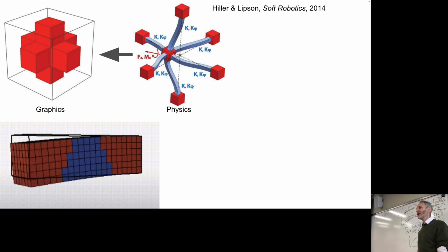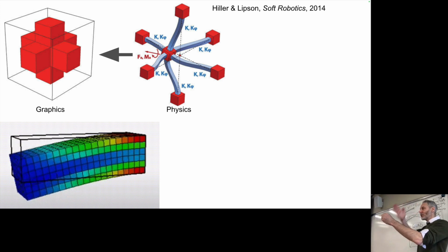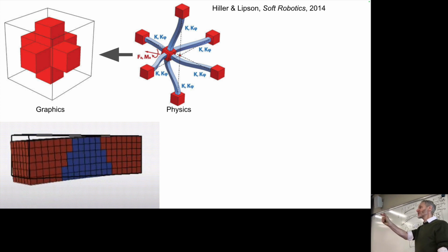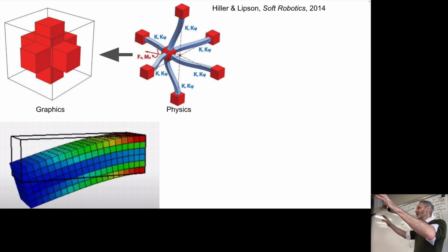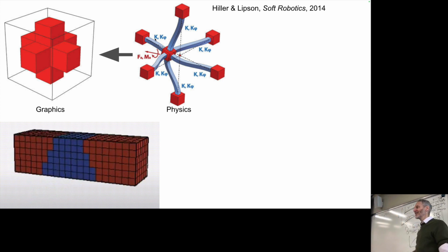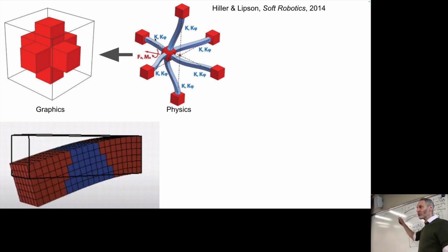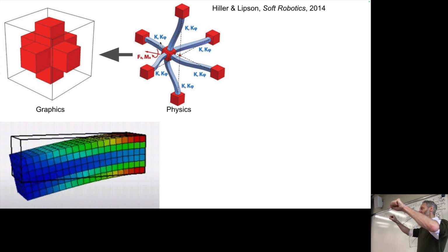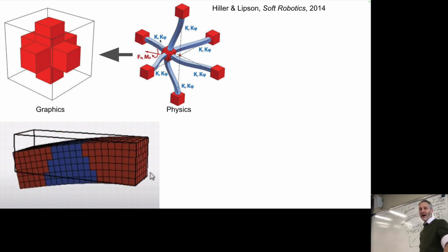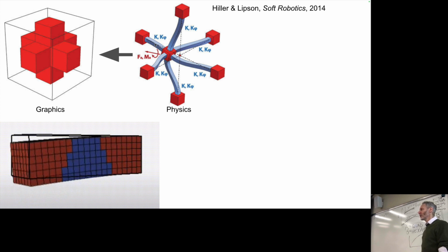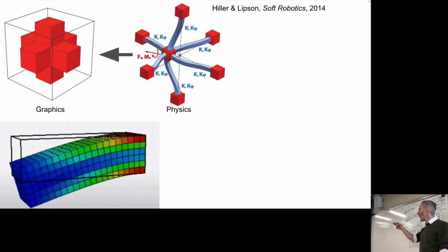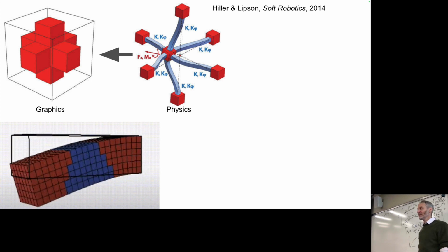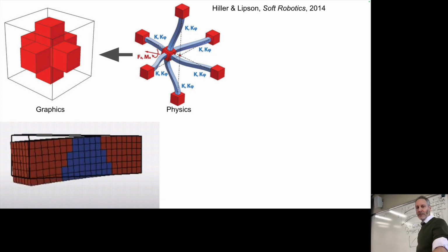That's its resting length. If we take a spring and cut it in half and put a little piston in the middle, and that piston can expand and contract, we are in essence increasing or decreasing the resting length of the spring. So in the robot you just saw in the video, the CPG is increasing or decreasing the resting length of the springs that connect neighboring voxels together. That's how actuation occurs in the soft robots that are simulated in VoxCAD. Everybody see that? Okay.